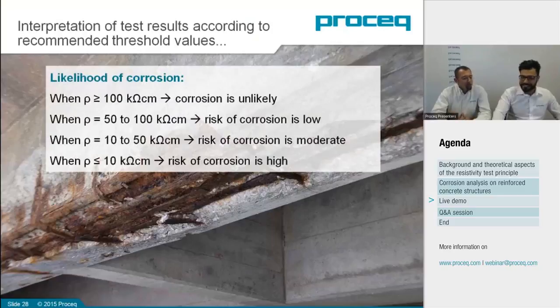Now, a first approach is just going straight to your result, to your table of your resistivity. I'll just look at the resistivity in itself. That's where literature helps. And, well, is it rusting? Is it not? Here's the first criteria to assess the likelihood, which is very important. So, technically speaking, for this one measuring point we have an indication of a moderate risk of corrosion.